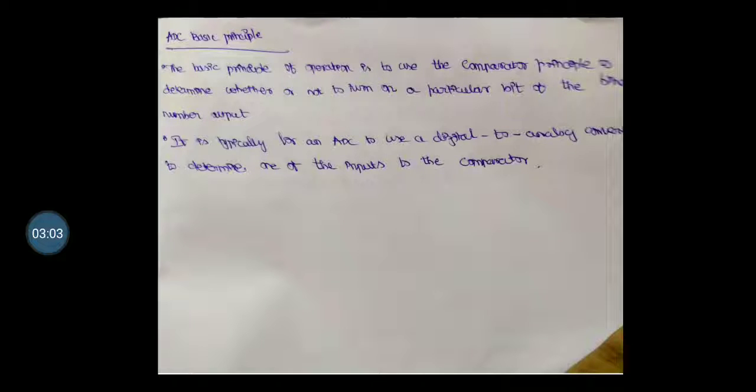Thus the AD converter performs exactly the opposite function of a DA converter. It accepts an analog input voltage VA and produces an output binary word D1, D2, D3, etc., of functional value D, such that D is the summation of all the binary outputs.